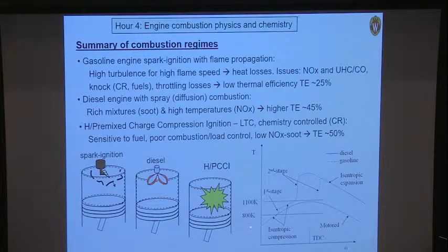For a fuel like diesel, which is very easy to compress ignite, in other words, at relatively low temperatures, what you see is you compress, and then it's actually a two-stage combustion process where you have some initial heat release, which makes it even worse. Now the temperatures are higher during the rest of the compression until the second stage takes off. And now you have much earlier combustion. So diesel is just not a good fuel for an HCCI engine by itself. And we'll talk more about that later.